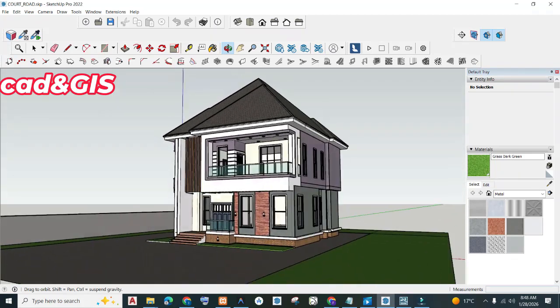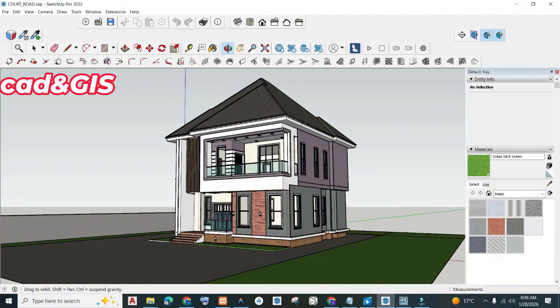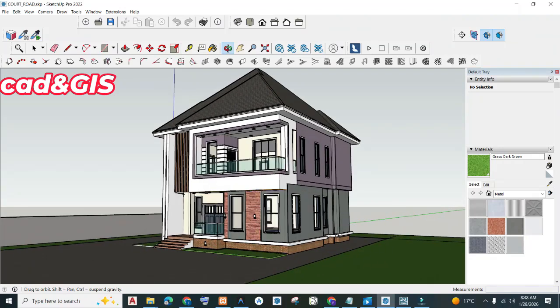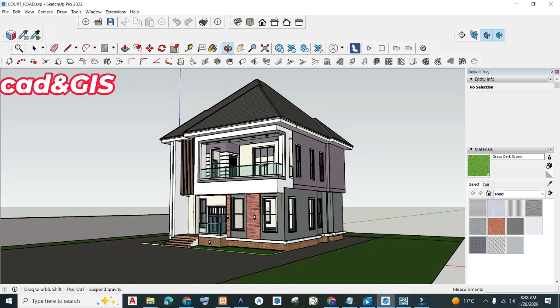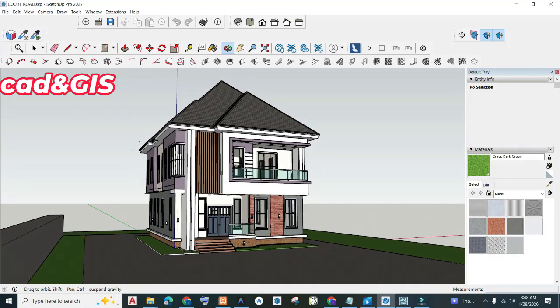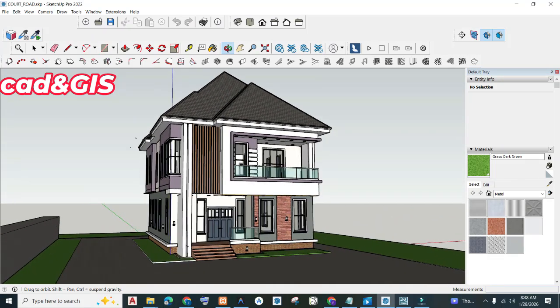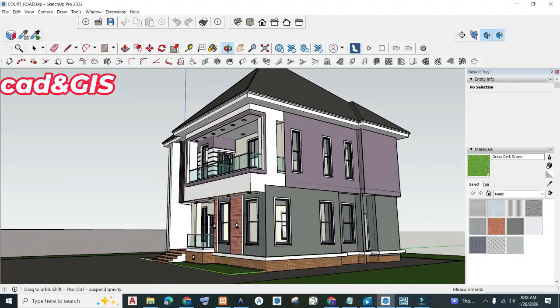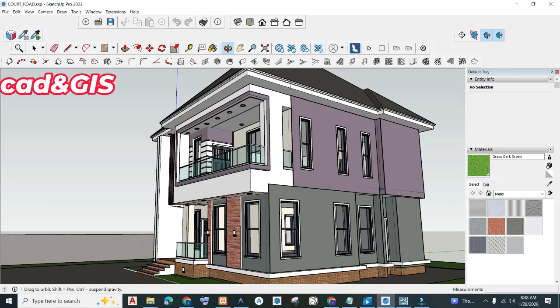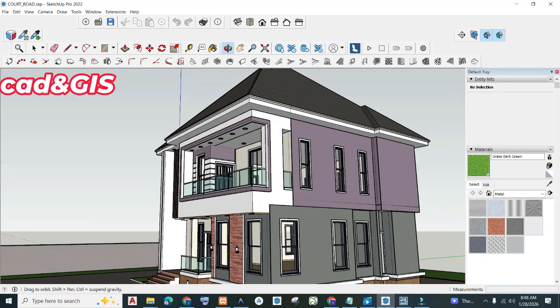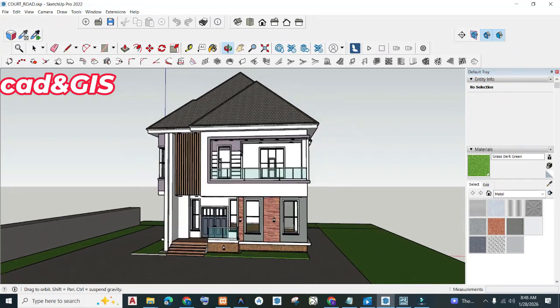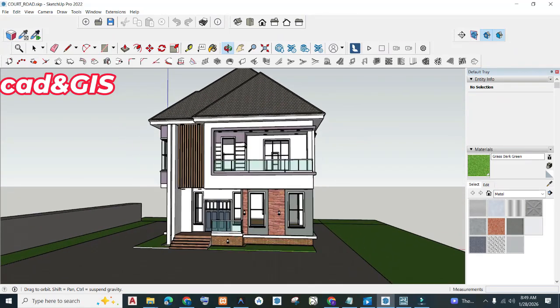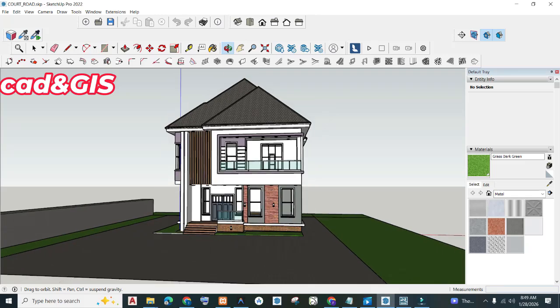And it's going to be like a form of color ID. It's going to split them into color, so the parts will be grouped based on the color that you sent to Lumion. Because Lumion is not a modeling software, it's a rendering software, so it cannot detect models easily. It can only detect surfaces that have material. And if you export any object that has one particular material, it's going to consider that object as just one complete block. So that's how Lumion treats models.